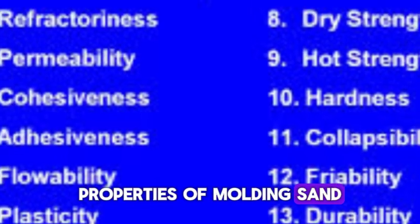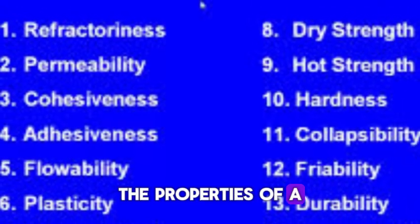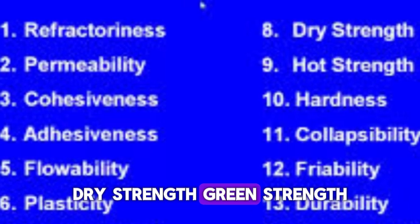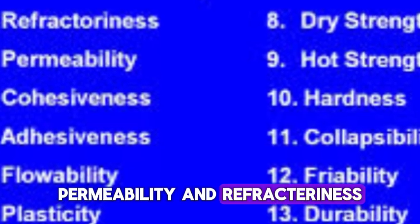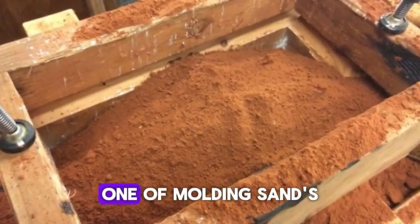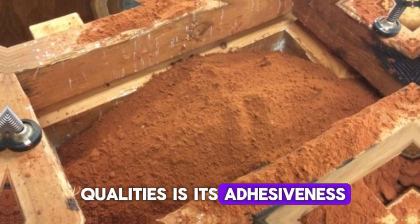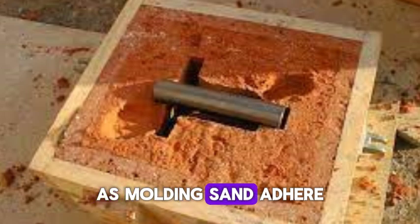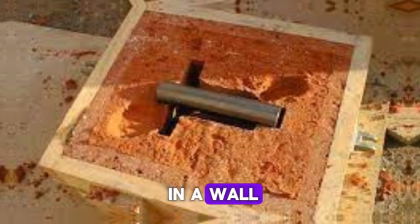Properties of molding sand. The properties of a good molding sand are adhesiveness, cohesiveness, collapsibility, flowability, dry strength, green strength, permeability, and refractoriness. 1. Adhesiveness. One of molding sand's qualities is its adhesiveness, which allows it to attach to or adhere to other objects, as molding sand adheres to the molding boxes in a wall.